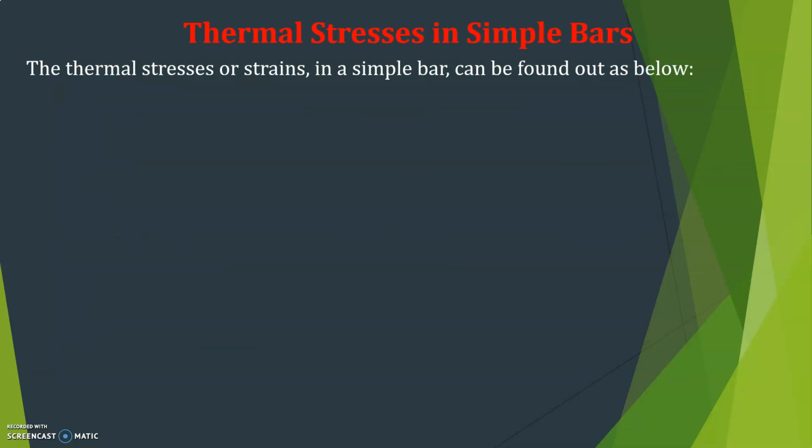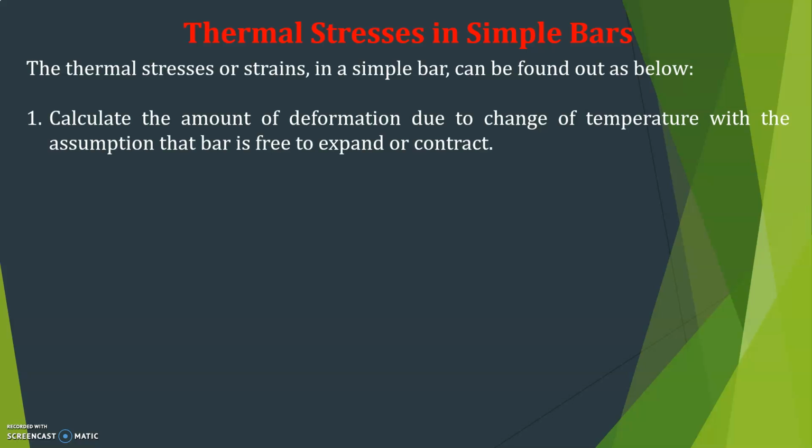Okay, then how can you find the thermal stresses and strain in the case of a simple bar? We will see that. First, you have to calculate the amount of deformation due to change of temperature, with the assumption that the body or bar is free to expand or contract.